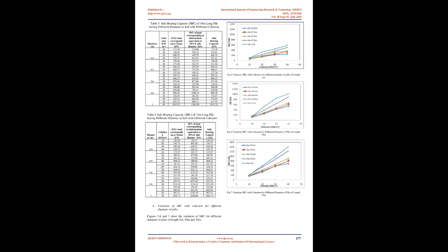The piles are modeled as embedded beam elements with a special interface element. The pile-soil interaction for an embedded pile involves a skin resistance and a tip resistance. The input parameters required for modeling the soil are modulus of elasticity, Poisson's ratio, angle of friction, dilatancy angle, and unit weight of soil. The modulus of elasticity of cohesive soil has been determined as per the following relation.